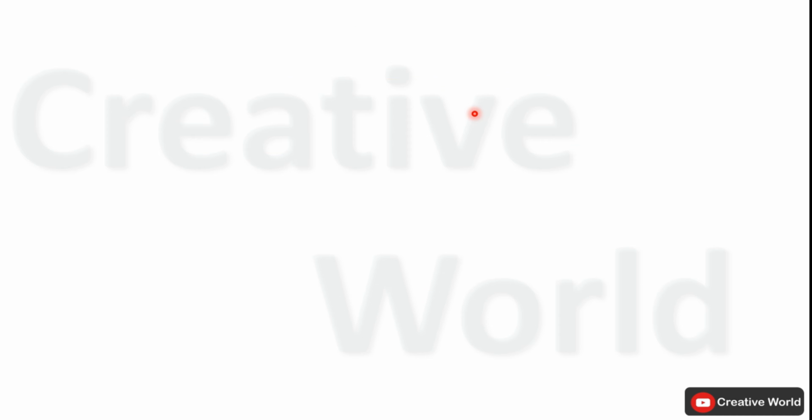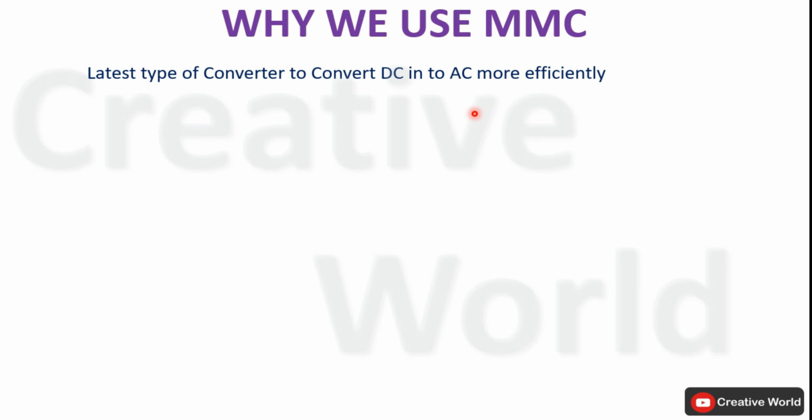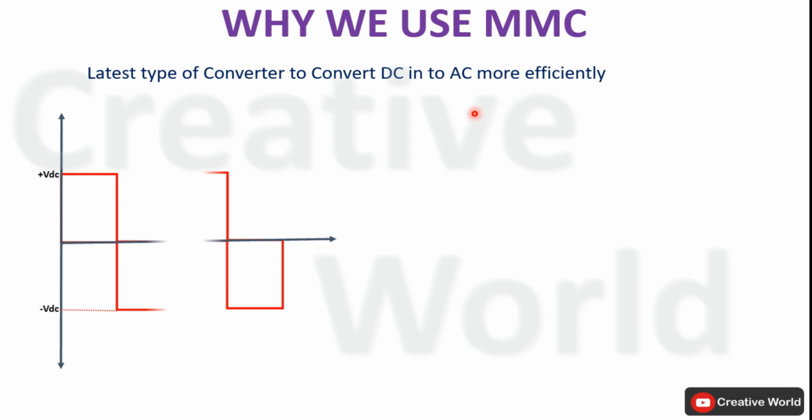Next, a question may arise: why do we use MMCs? To answer this question, I have given some prominent reasons, but there are many more. The first reason is that these are the latest type of converters, which convert DC into AC in a more efficient way. A conventional two-level inverter, which converts DC into AC, has only two levels: positive VDC and negative VDC. Here VDC is the required output AC peak voltage.